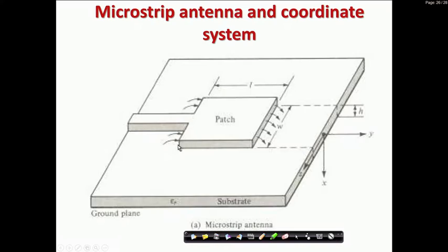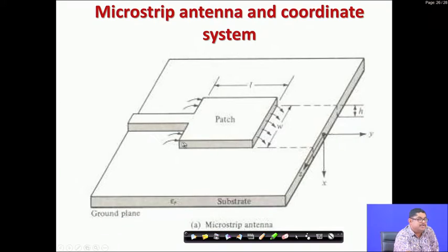So, there is no radiation from the parallel plate waveguide. Only the fields radiate at these edges, because here the parallel plate waveguide suddenly has an opening. So, the aperture is this one, that side there is another aperture. So, I have now simply two apertures, this is one and this is another. This waveguide's dimension L is cleverly put as lambda g by 2. Lambda g is the guided wavelength, that concept we have seen in case of any waveguide.